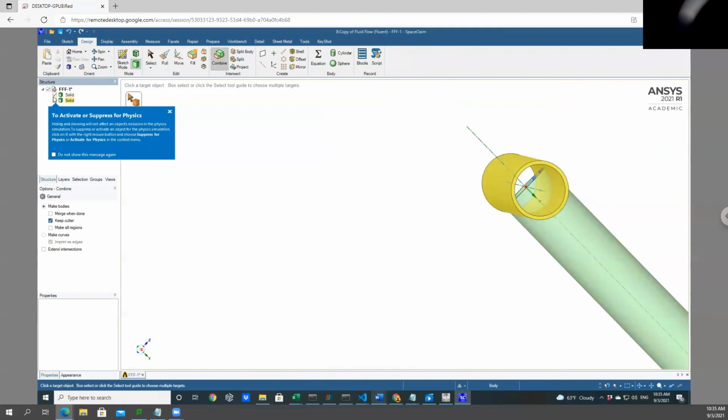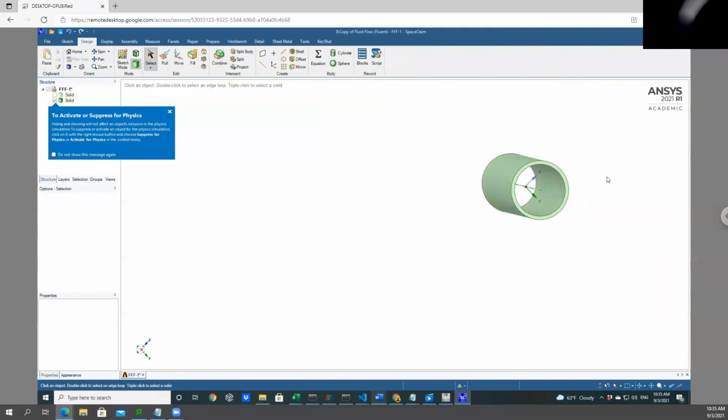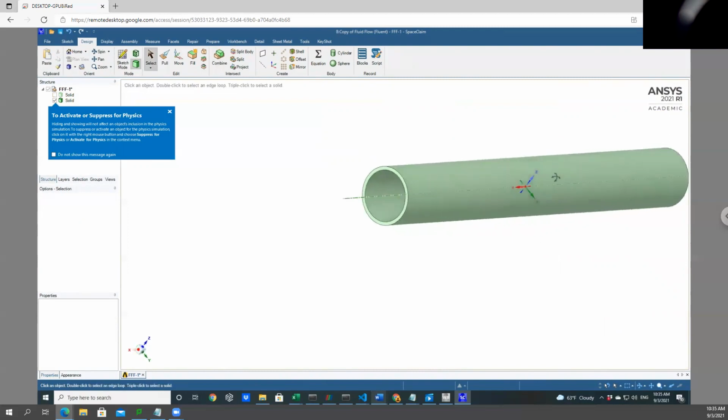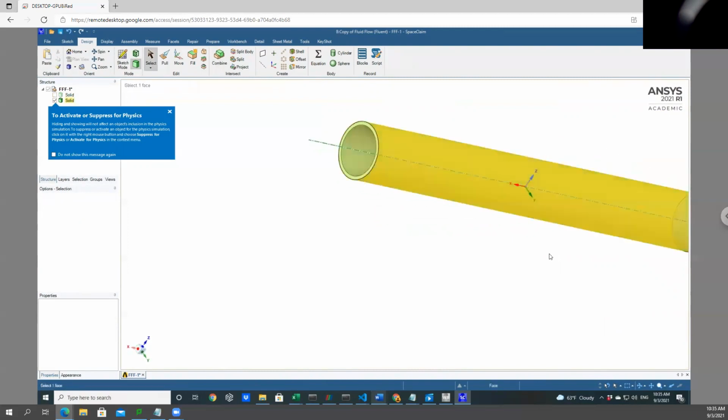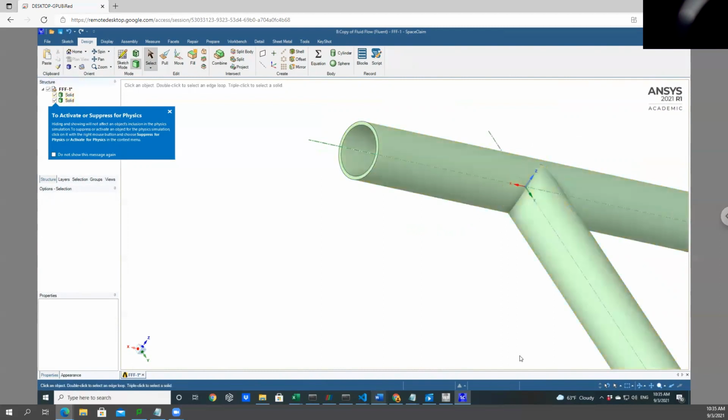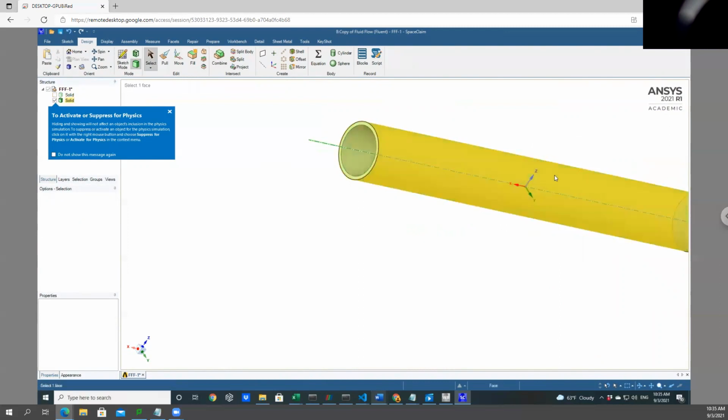If I check this, and I uncheck this, I am able to see the horizontal vessel, right? So see, if I rotate the horizontal vessel, it doesn't have a hole. So if blood flow is coming through the vertical vessel, it will face this wall, right? And flow won't go through the horizontal vessel. So actually, we need to cut that part of the horizontal vessel.